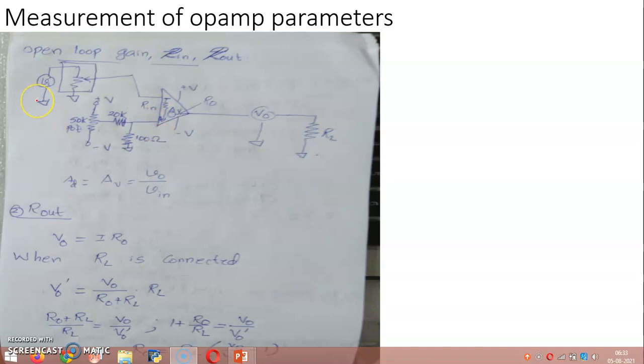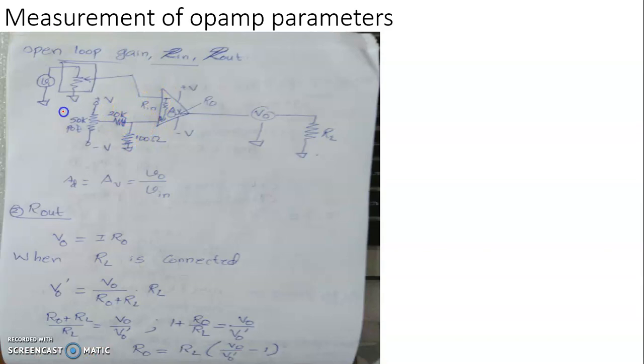And before you can supply the signal either into the inverting terminal or into the non-inverting terminal. I am supplying the signal here to the inverting terminal, so to the non-inverting terminal I will have to account for the application of input offset voltage using the universal balancing technique.